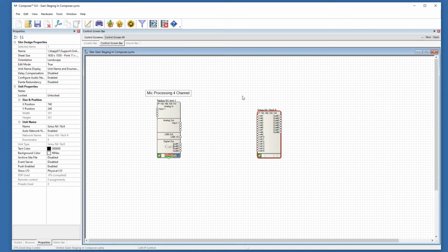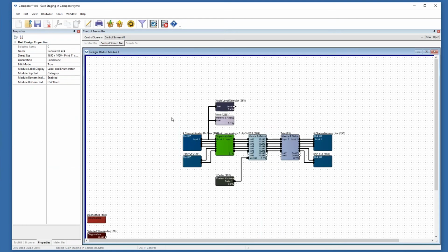I've calibrated it to like a +4 dBu, and to negative, I believe, if memory serves, -16. And then we have a noise generator and a tone generator, both set to +4 dBu reference. It's a very, very easy program.